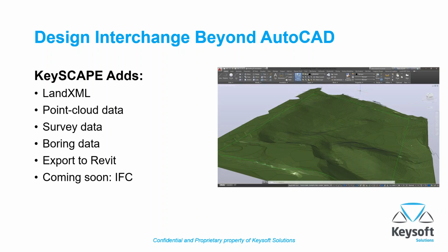So having all this enables you to work in a more accurate, quantifiable environment. It allows for better design decisions. As I move forward, you'll see that many tedious processes throughout analysis and design phases, things like interpolating contours, identifying spot elevation, slope analysis, or even locating plant material not only in the XY coordinates but also in the Z coordinate for preparing 3D renderings, all these are optimized once you're starting to work with surface models, and that all starts here with your base data.